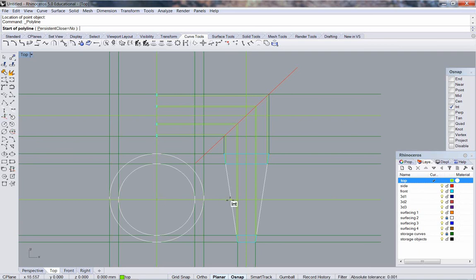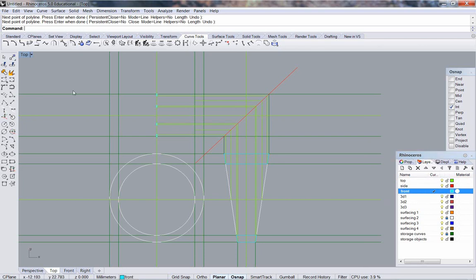I'm looking straight on, and I only have the one width. Up and over, and carry that into the full thickness of the cross section. Up to miter line, intersect, intersect over to full thickness of the shank. And we can draw that cross section.